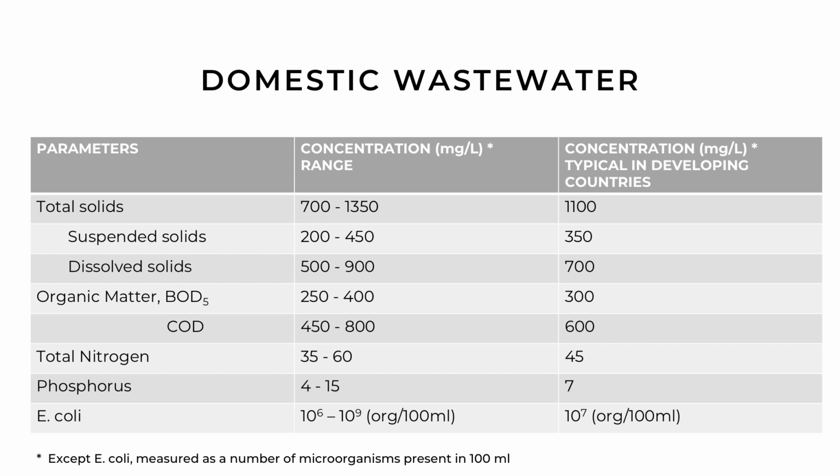You will need to take samples of the wastewater you will treat and get actual values for these indicators in a local laboratory. The aim of wastewater technologies is to decrease these concentrations to a level that is either required for discharging the water into the environment or the goal of reuse, such as irrigation water or drinking water standards.